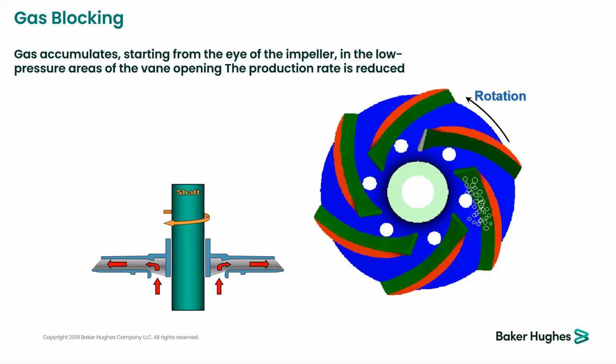In the area of the lowest pressure in the impeller, the liquid flow will not be able to drag the gas accumulation out of the low pressure area. Under that condition, the gas will start to accumulate as shown in the photos on the right-hand side. This design is applied for both radial and mixed flow stages in order to improve gas handling.